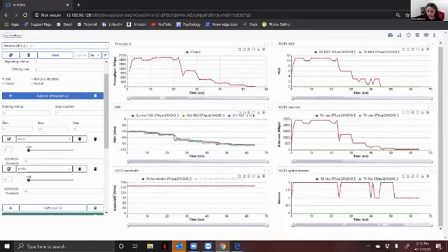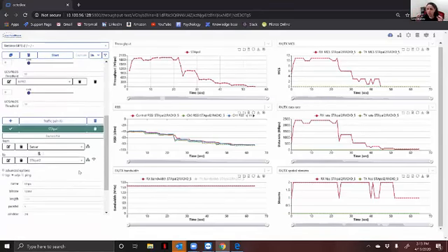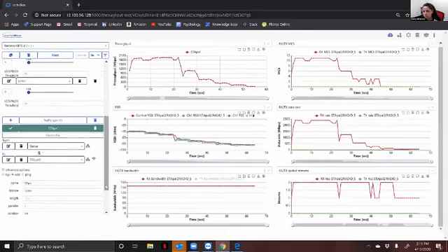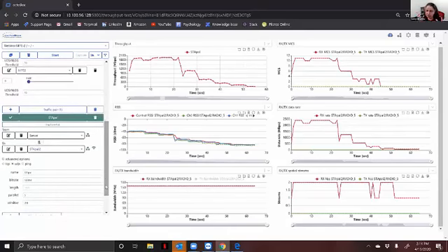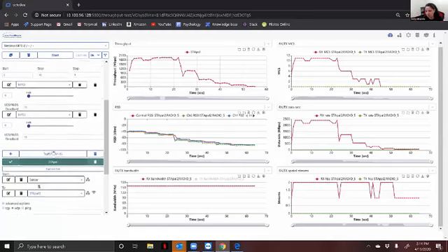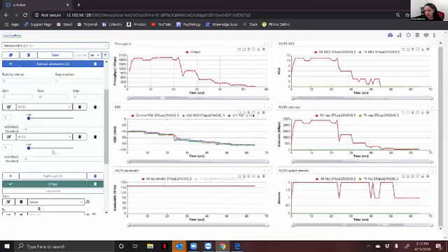Prachi, there's a question: who reports the RSSI? Your power sensor. Prachi is running, we have some slides with the test configuration, but she's using one of our instruments we call a PAL. This is running between the StayPal, a PAL based on the station chipset that we have, and an ASUS AP, correct? Yes. Through 2 MPEs, we have 8 paths through them. So we will show you the setup. And the PAL is reporting the RSSI.